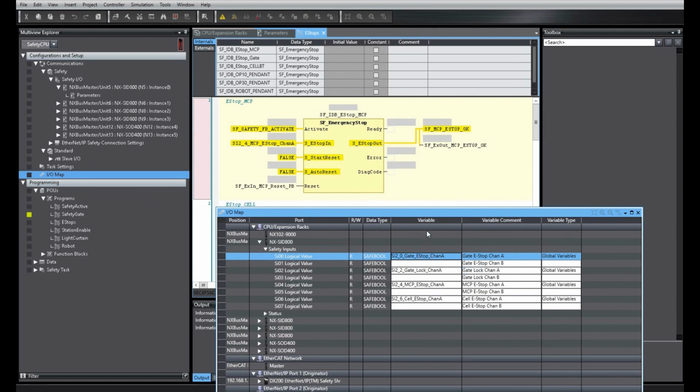This named variable will be used for the programming. Because the hardware configuration already bundled these 2 channels together, when we program we only need one channel name in this safety logic. So using this tag, it addresses the physical channel on this physical card.